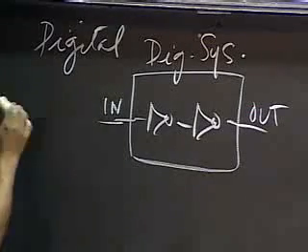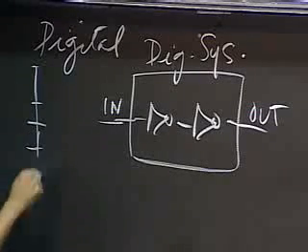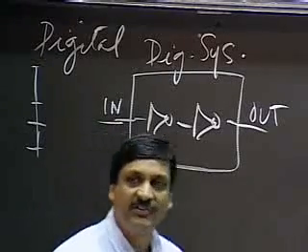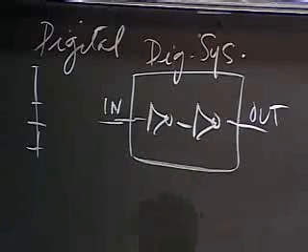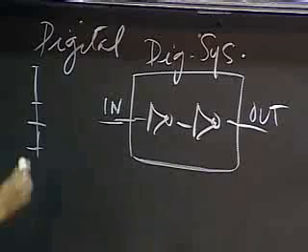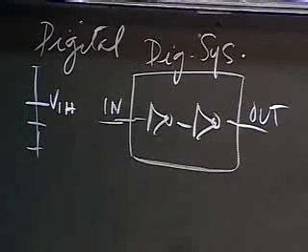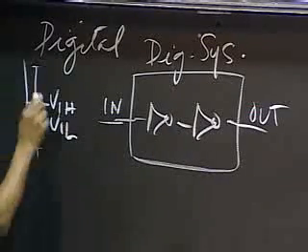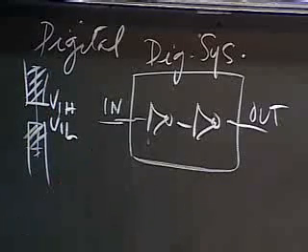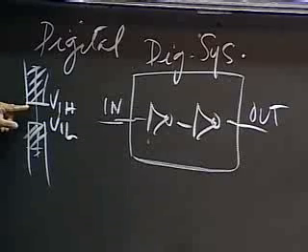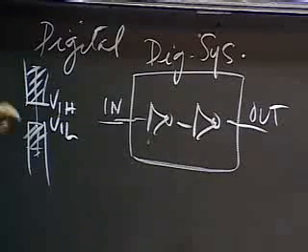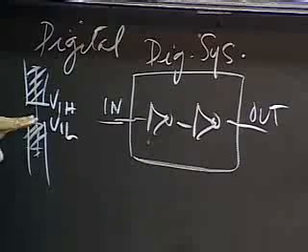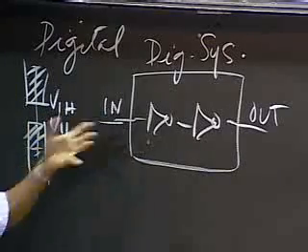And the discipline we described comprised of signals adhering to certain voltage thresholds, so that all the components in the system could agree on what comprised a 0 and what comprised a 1. Okay? So the way we did that was we said that we would have a threshold called VIH, V input high, another threshold called VIL, V input low. Okay, and we said that this circuit must recognize signals that are higher than VIH, 3 volts, for example, as a 1. And simultaneously, any signal that has a voltage level less than VIL, say 2 volts, should be recognized as a 0. Okay, that was the input constraint.